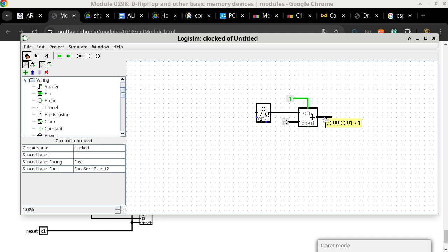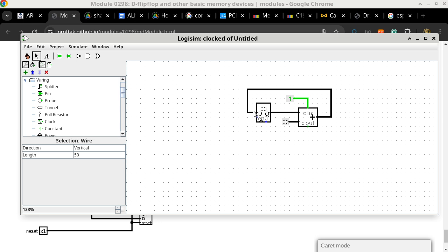Okay, not really surprising. So now we hook it up, we connect the wire all the way back to the input of the register. In other words, we just go all the way around here to the D port, and nothing happens, because someone would think that this is going to go crazy. The circuit would just keep going from 00 to 01 and then all the way to FF and back to 00 again. Nope, nothing is happening. Well, for two reasons. One, it's not enabled. Two, it's not clocked.